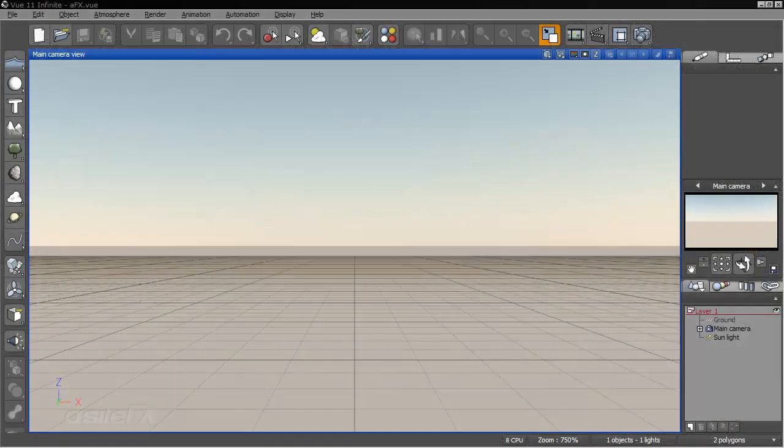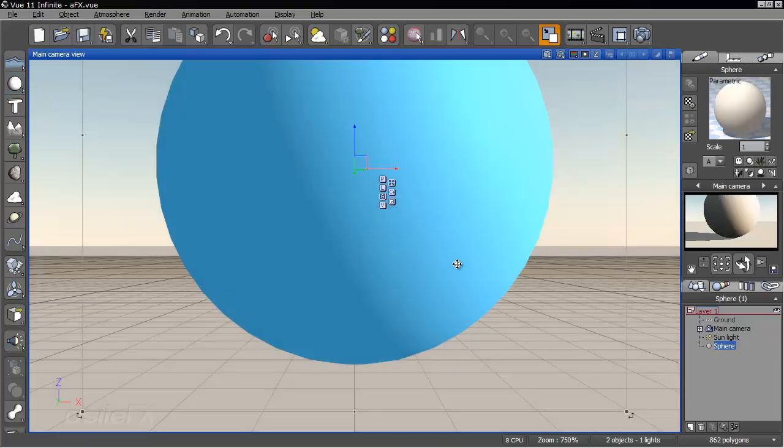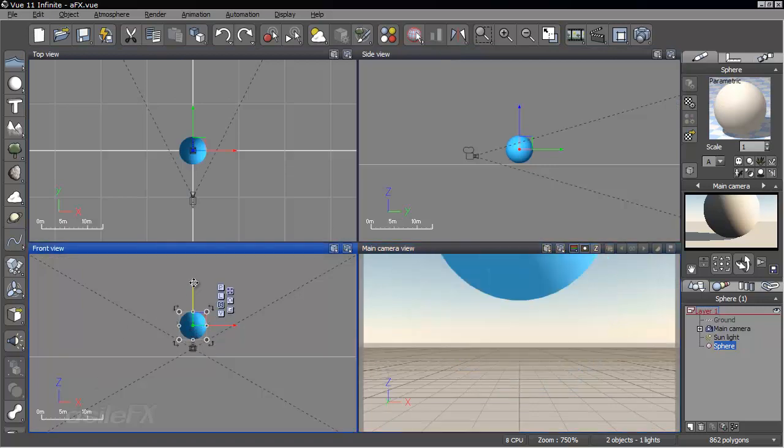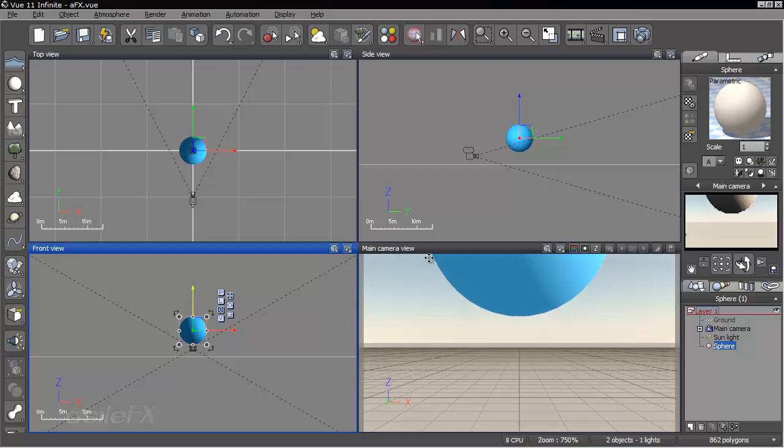I'm now going to be showing you ecosystem particles, emitters, and global particle options. What we need first is a surface to emit particles from. Particles are emitted from the surface normals of an object that has an ecosystem particle emitter assigned to it. So I'm just adding a sphere to the scene. And what I also want to do is raise this up above the ground, because we're also going to be taking a look at collisions.